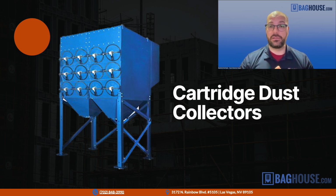So cartridge collectors, this terminology is important. Cartridge collectors use cartridges instead of bags. So instead of a bag that's 6 inches by, say, 10 feet long, the cartridges are usually 12 to 18 inches in diameter and maybe 20 to 40 inches long.